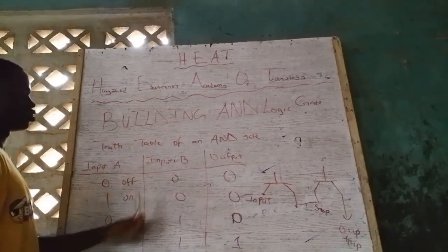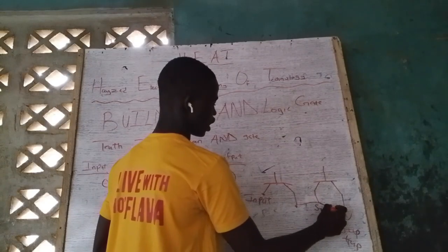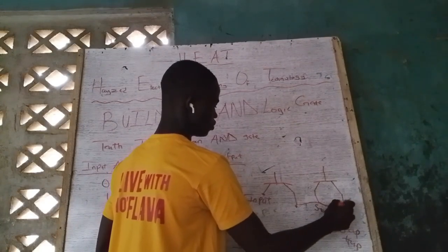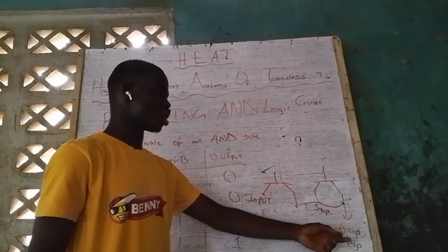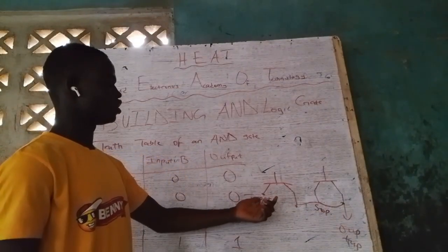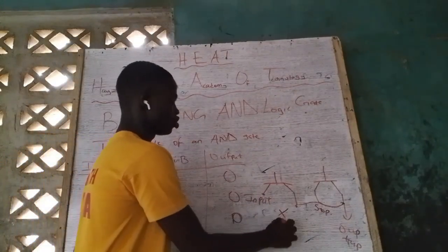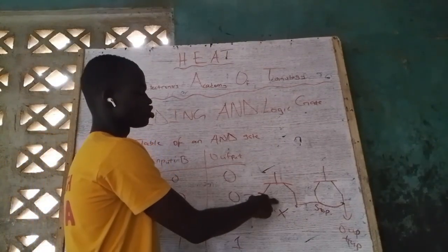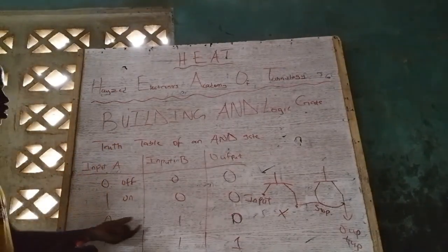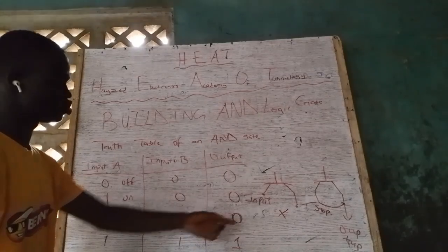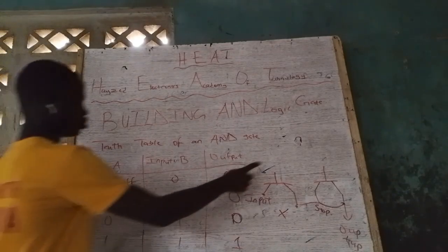But transistor B was turned on. That means we can have these two guys connected together. Yes, this whole place is connected to the output, but the main input, the main signal we want, can't pass through because transistor A hasn't been turned on yet. That means that if transistor A is at 0 and transistor B is at 1, the output is going to be what? 0.